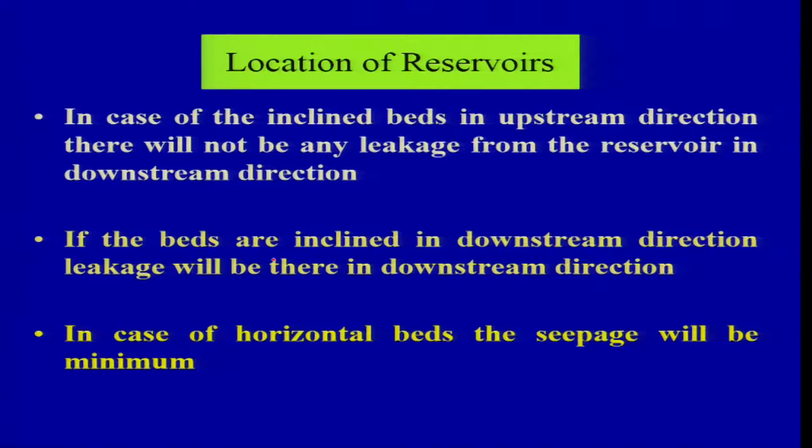Now, if the beds are inclined in the downstream direction, then you will face problems with leakage, and we have discussed why this site is not ideal to be put. In case of horizontal beds, it may be minimized. In any case, if you have folds like this, as we have talked about, this may be the ideal one to put, but this is not at all. This will result in slippage and all that.